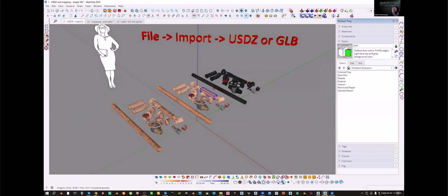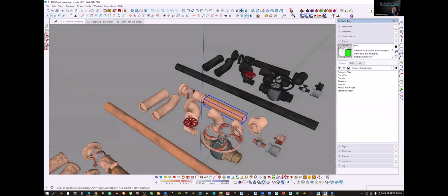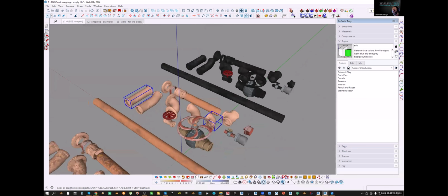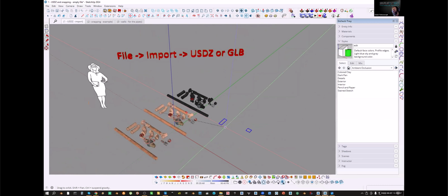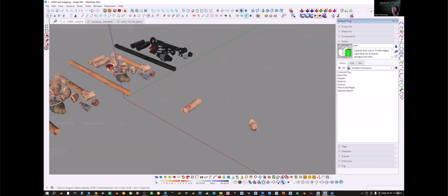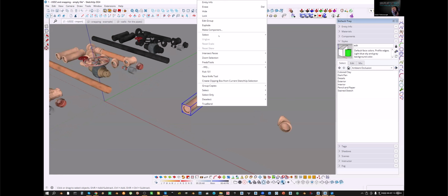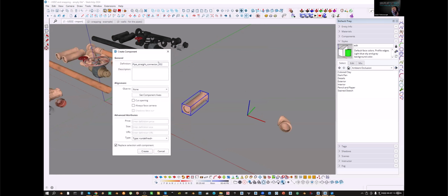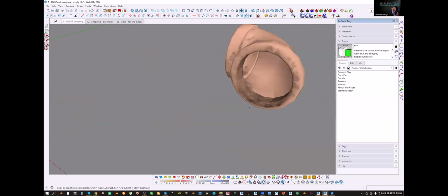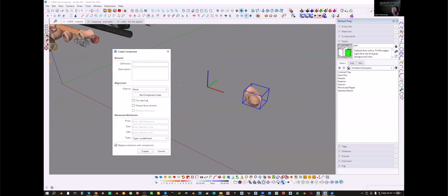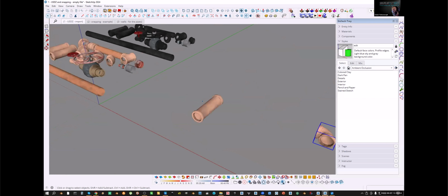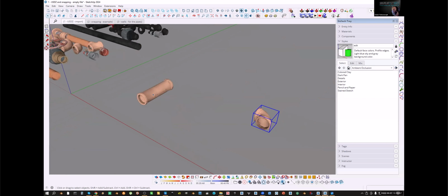So going back to the model, I'm going to do just two objects for the snapping, because I prepared the scene so that I already have those objects here, but let me show you for the ones who don't know how those snaps work. Let me first make that a component. Oh, one more time. Let me add one number. All right, and now with the corner pipe. Once it is a component, because you don't want to work with groups, because if you add the snaps first and then make a component from the group, the snaps will disappear. So right away you want to make them components.